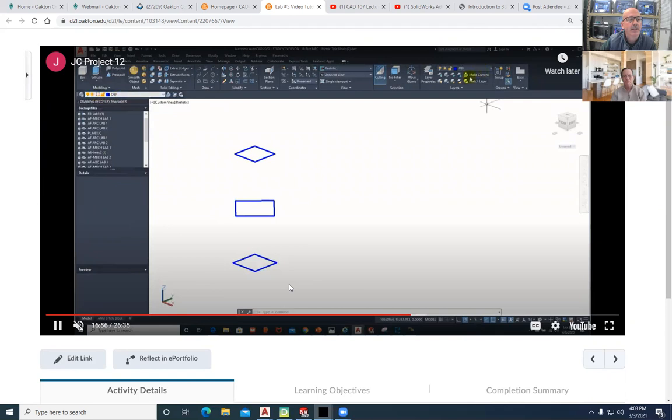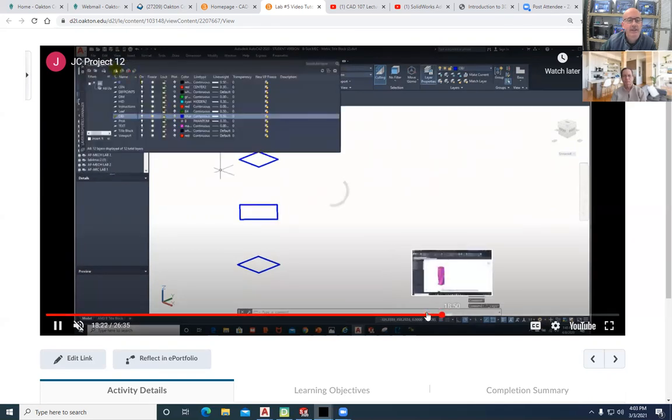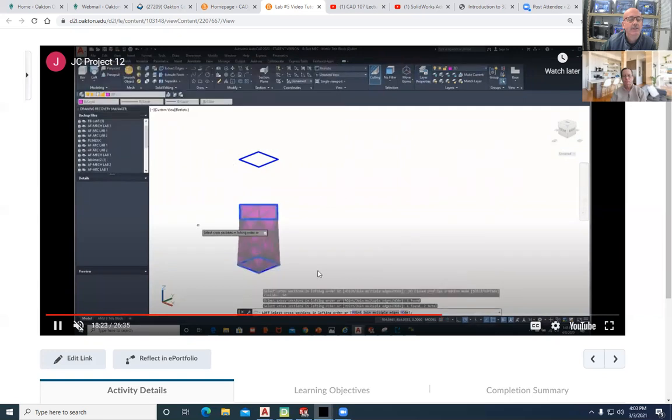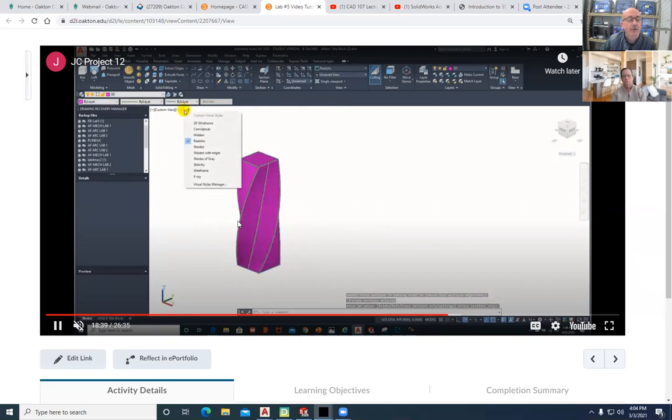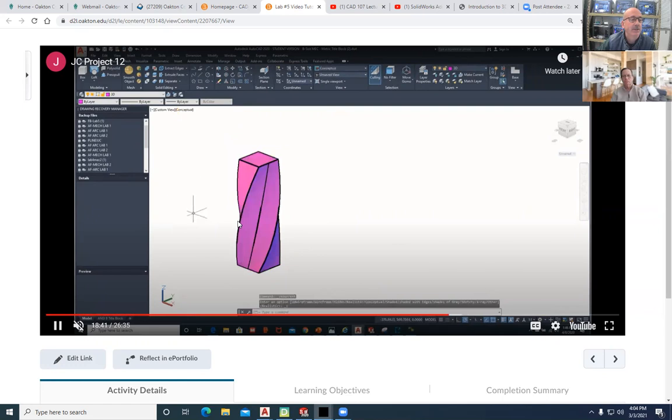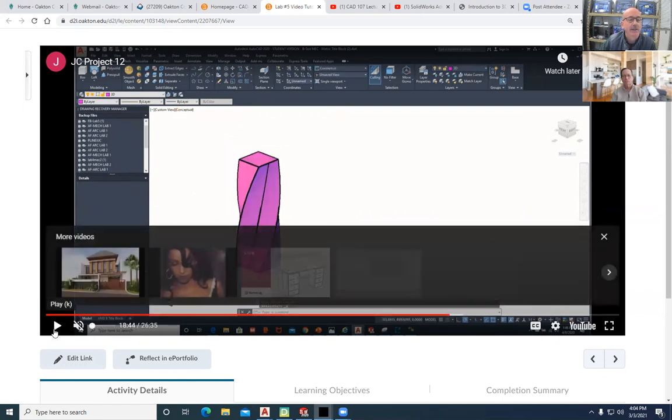I do a lot of talking in these videos. Or you can type it in, either way you like to do it. Right. And so I'm just going to cut to the chase here because it hasn't done it yet. And there it goes. And so we show how to loft the objects. And then we show you how to export it. And we'll be printing that with what's called Spiralize Outer Contour, which allows them to print very fast some very big shapes. And so vases are really a neat project.